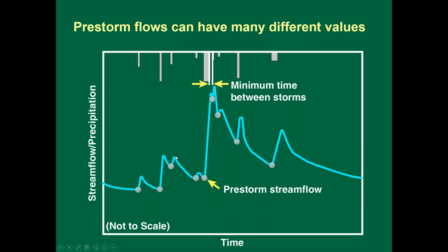And then again, we have stream flow recession, and another small event starting, but then you see that we have these large events. In a stream basin, it can take days for a storm flow hydrograph to move by. And as we said, if we're looking at hourly precipitation statistics, you could have three one-hour storms in a 24-hour period. So very often your next storm flow hydrograph occurs on the back of a previous storm.